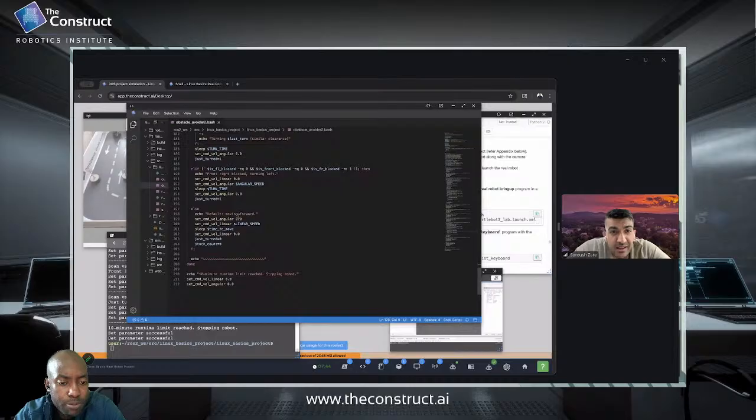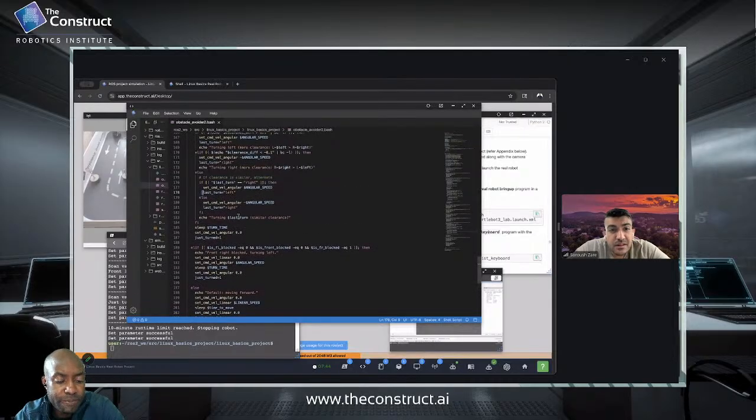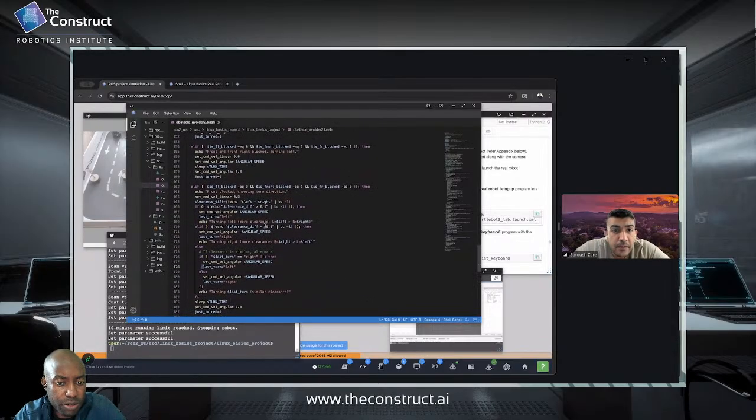So in these moments, are you setting the linear and angular velocities to zero when your robot has to make these decisions? Do you have the moment where it has to set these values to zero and reconsider which parameters to set linear and angular velocity to? Yeah, here for example, first I set the linear velocity to 0, then calculate the difference, and then assign the angular speed for the fixed amount of angular time.